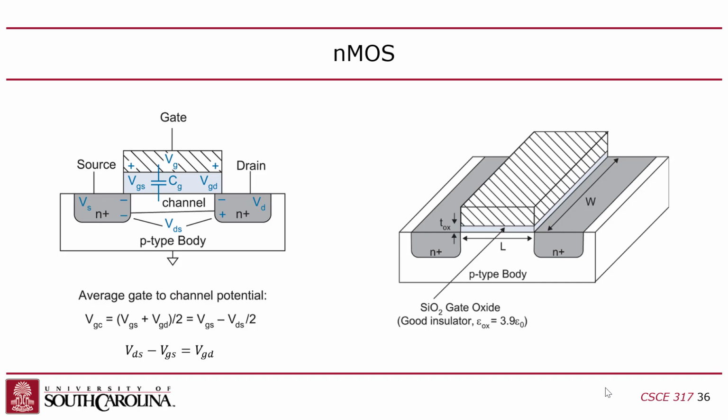The fabrication technology node does not relate directly to this channel length anymore. And the reason is that 4 nanometers is like 8 atoms. That's really small, right? But the idea is that you want to make that channel as small as possible, because the smaller the channel is, the faster the charge carriers get across the channel to carry the current.